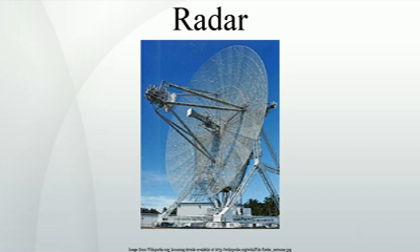Engineering. A radar's components are a transmitter that generates the radio signal with an oscillator such as a klystron or a magnetron and controls its duration by a modulator, a waveguide that links the transmitter and the antenna, a duplexer that serves as a switch between the antenna and the transmitter or the receiver for the signal when the antenna is used in both situations, a receiver.